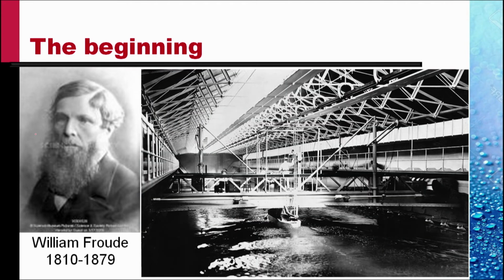This is a large scale towing tank where a model boat is being towed in a channel. The force required to tow it is read, and then from this the prediction is made of what the actual drag would be on the prototype.